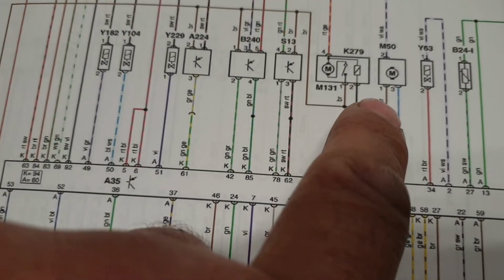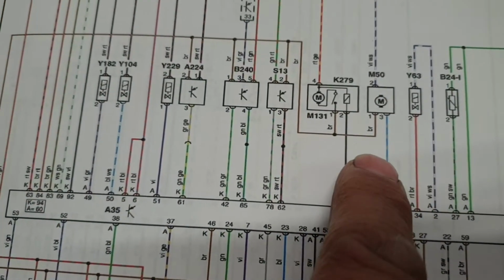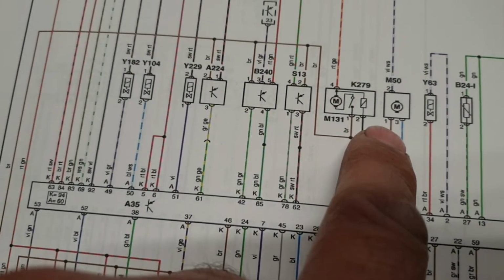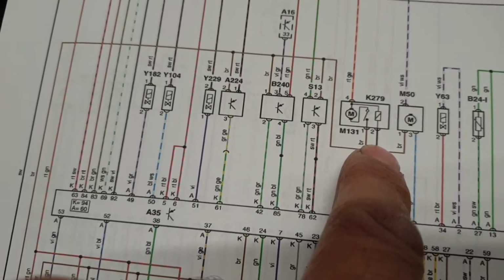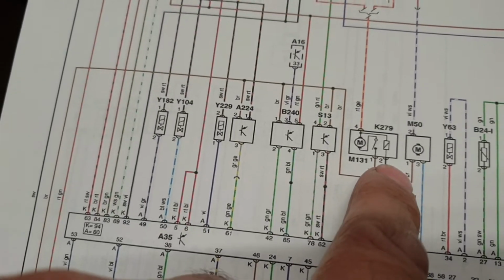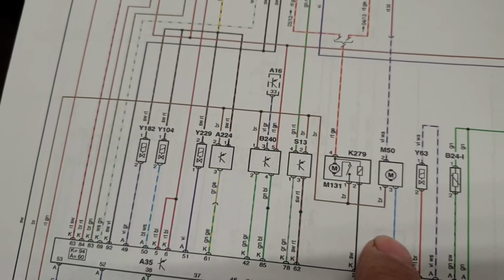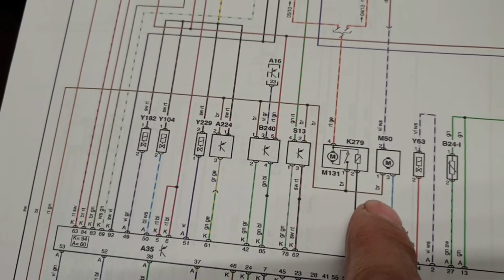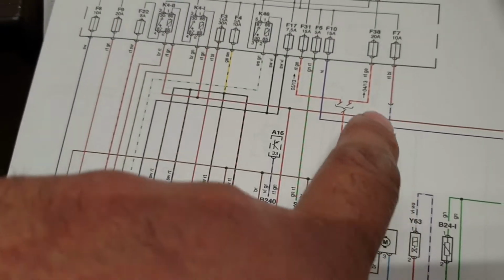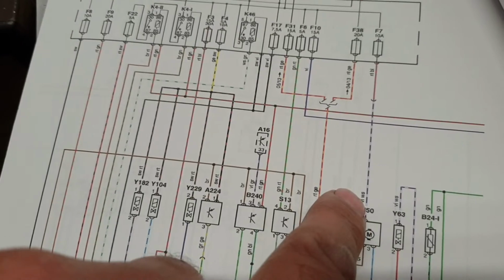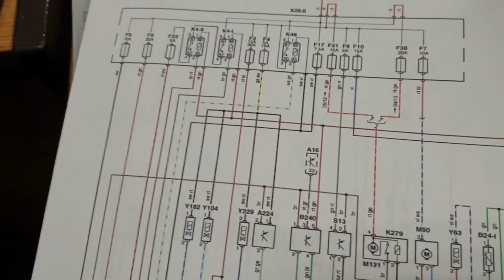The ground side was tested with the component connected, so the wiring connector was connected to the pump. The ground side had 0.035 volts, the control wire had 0.251 volts, and pin 2, the power supply side, had 12 volts or source voltage.